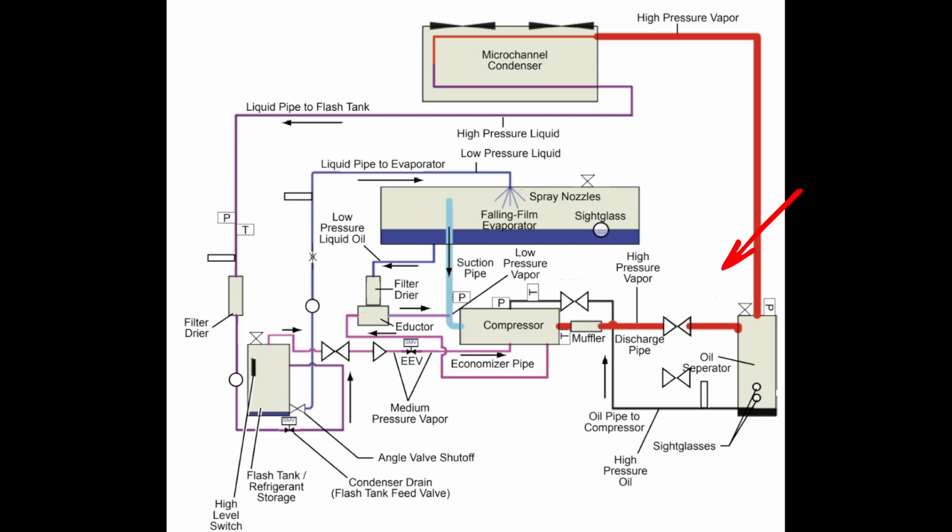So anyway, in a new system, we're coming off from over here. That's my point. Regardless, we come off of our discharge side and we're a superheated, high pressure hot gas refrigerant. And then we come into our eductor block. Now, this eductor block is exactly what I showed a minute ago via that diagram.